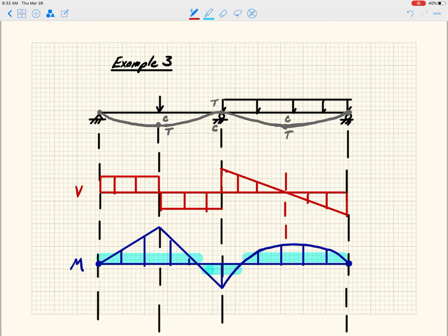But again, we don't have numbers here. I'm not plotting out exactly where it's crossing 0. I'm just looking at the shape, right? So if I run a simulation and it gives me this shear diagram and this moment diagram, then it would have numbers and we would have all these dimensions. I have a gut feel of whether or not that makes sense to me, or maybe I've made a mistake, or maybe I've asked the computer to solve the wrong problem. That's actually pretty common. Okay, so with that, I think we'll end this, and I will answer questions on this.